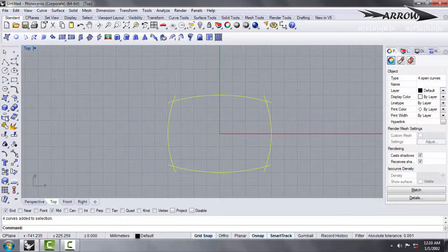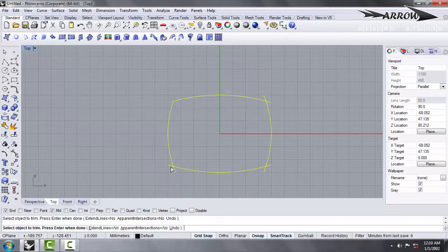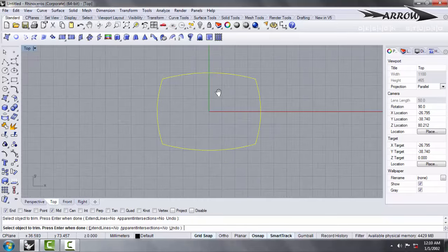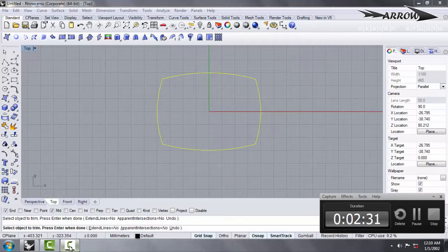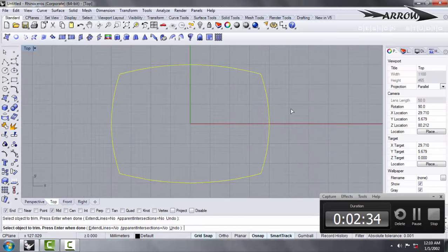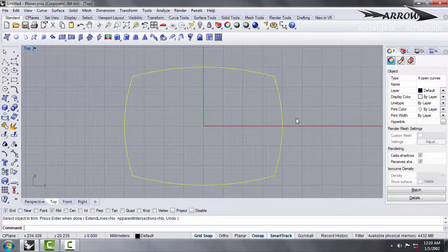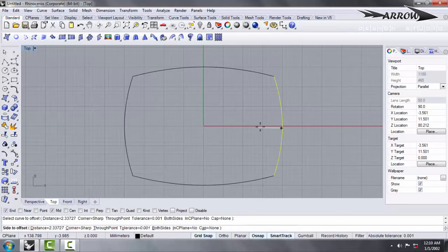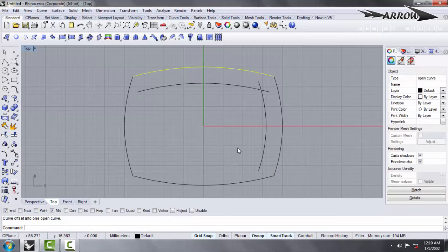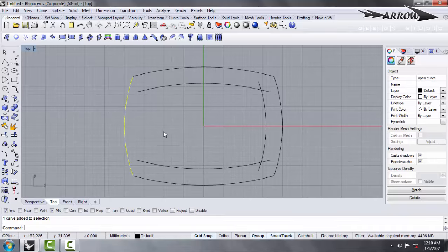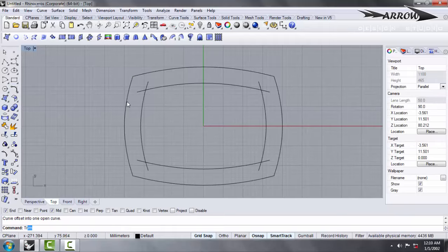I'll just delete this because I want this much area. I'll trim the sides over here, and this is my base. This thing is particularly my base, and what I need to do now is offset it. I'll say escape, I'll say offset, and I'll select the curve to offset. The draft angle should be just tentative, snapping to the points. I just want to make it a gradual taper. So these are the things that I'm going to do right now.